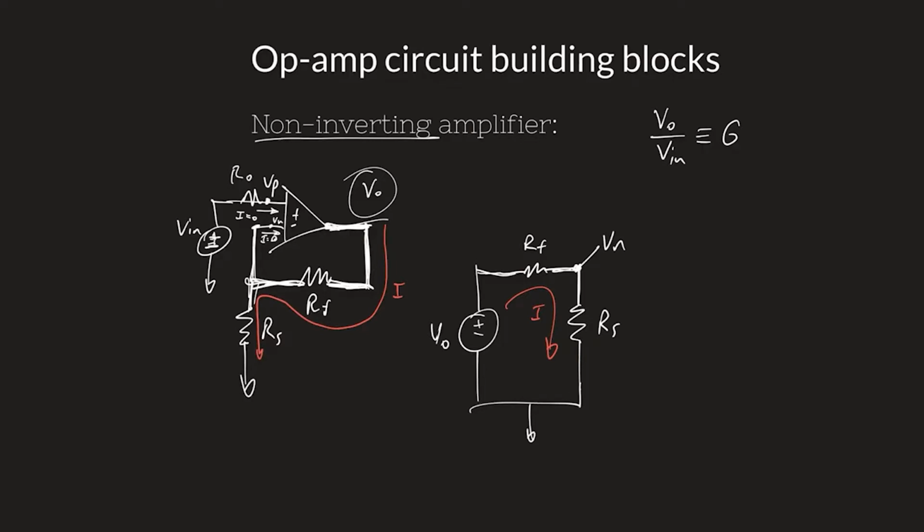The way I do that is to realize that this op-amp actually wants to do this. That's what it wants to do. If I just start with assuming Vp is greater than Vn, then knowing how the op-amp by itself works, if Vp is greater than Vn, because of this huge gain, I'm just going to hit the positive rail.